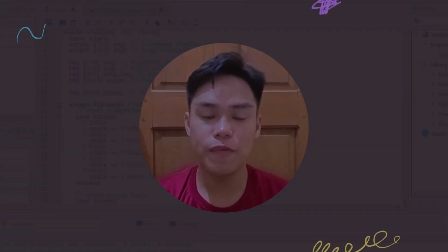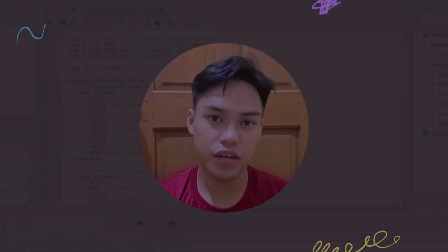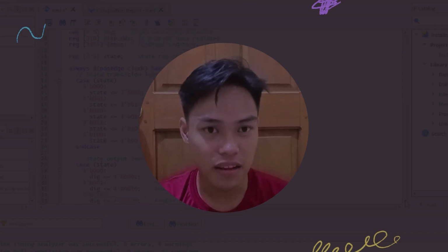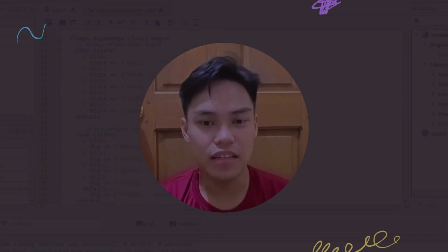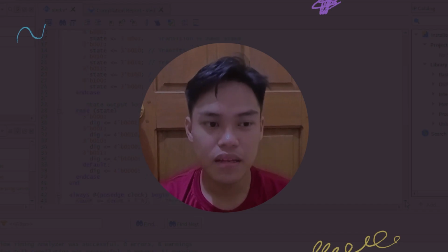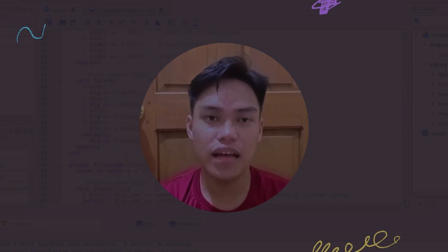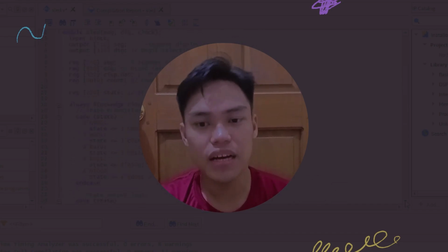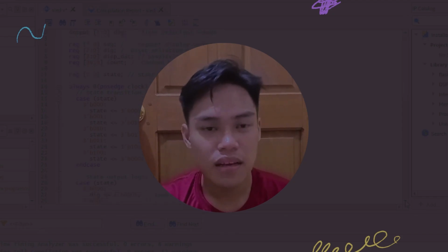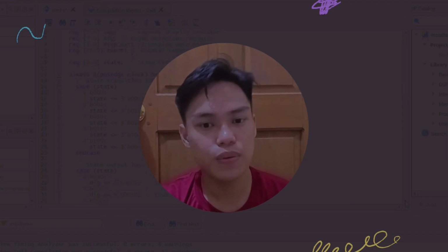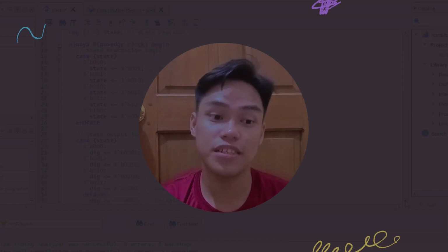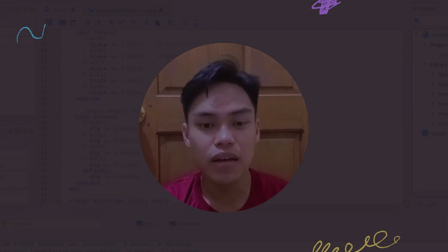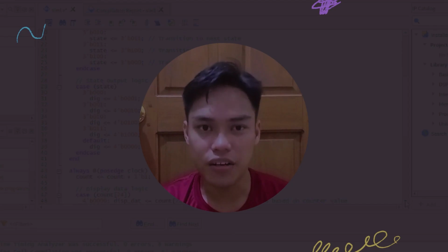All this code represents a synchronous sequential circuit because it uses a clock signal to control the timing of state transitions and data updates. The registers hold the state and data values, and their updates are synchronous with the clock. The circuit progresses through different states based on the current state and updates the display based on the count value and the current state.